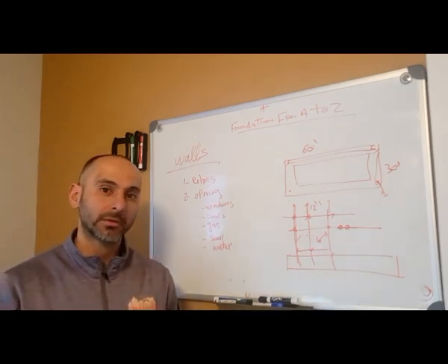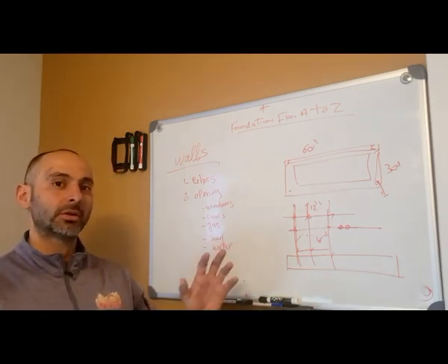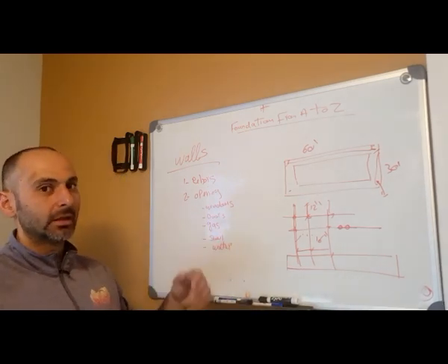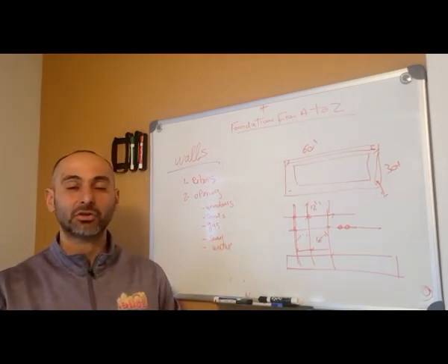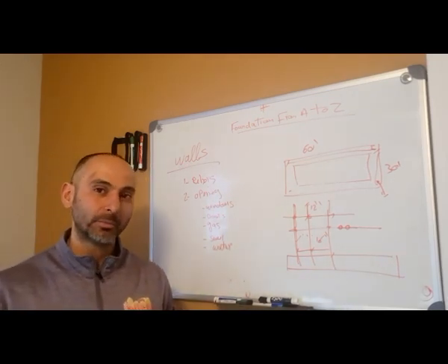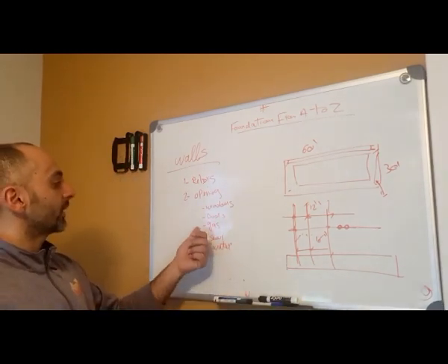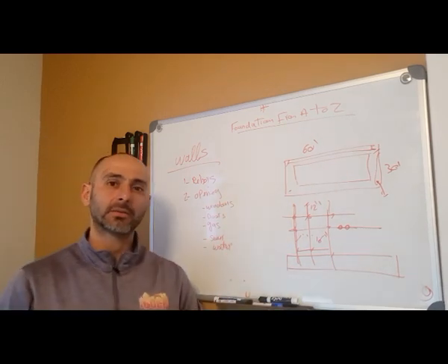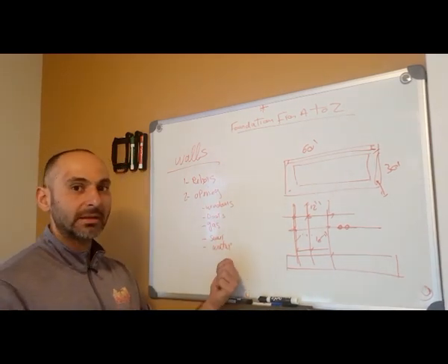When you put the concrete in, you're not going to be able to fix it, so make sure he got all the roughs right. Also ask him to give you half an inch, or a maximum of three-quarters, of play in each frame in case the window comes too big or too small. You have some room to play. Water, sewer, and gas can be done after the wall is bored, but it's going to cost you money in core drilling. It's not going to cost him anything to run all that stuff.